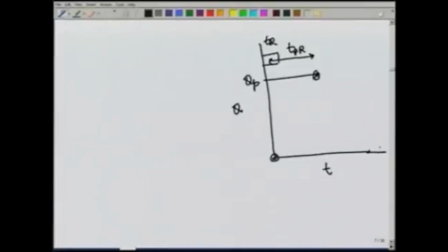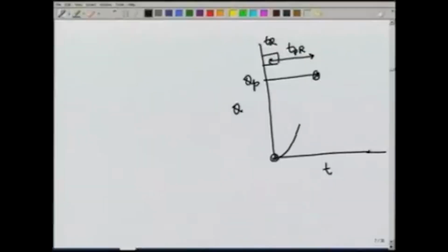The other information which we have is that the area under the curve should be equal to 1 centimeter of depth over the catchment area. So, we may have a shape like this, or like this. So, there are various other options also which all will have the same area. Therefore, some other points need to be given.